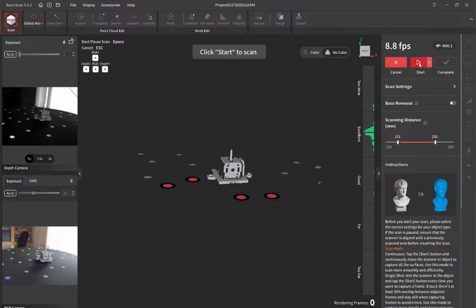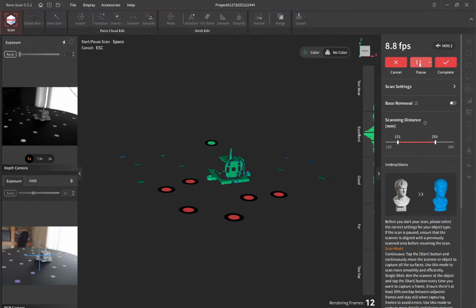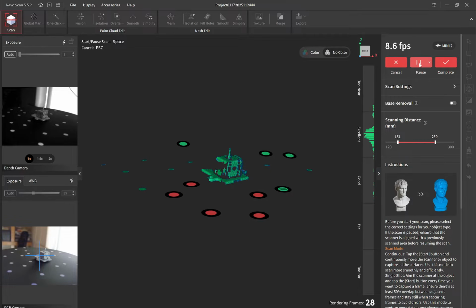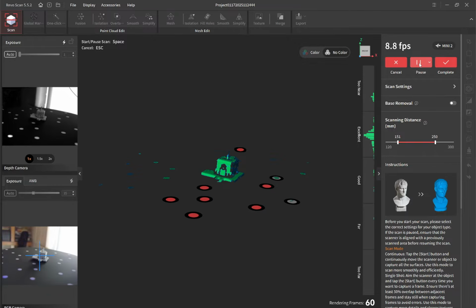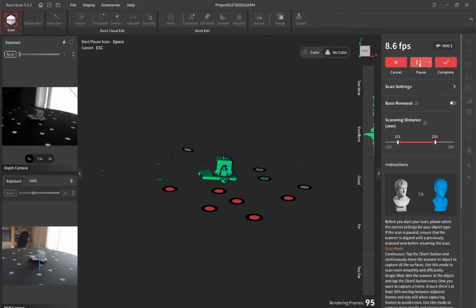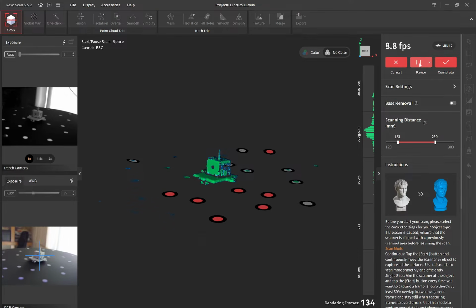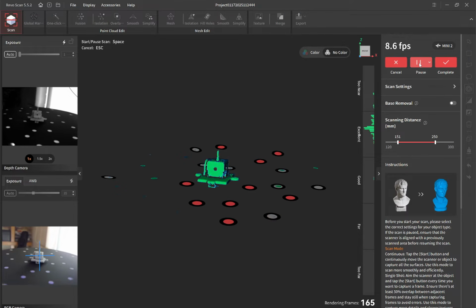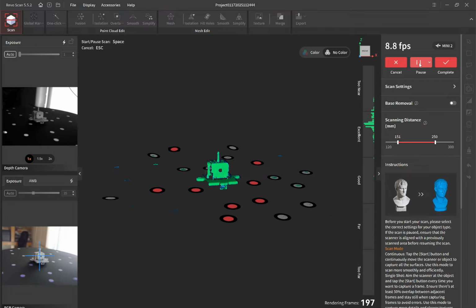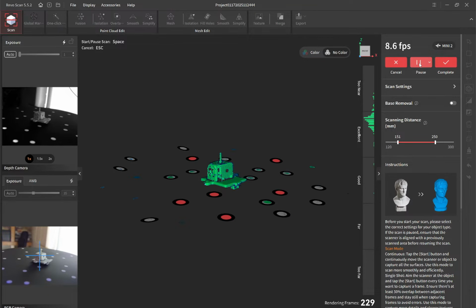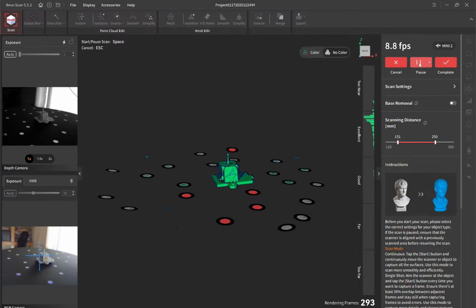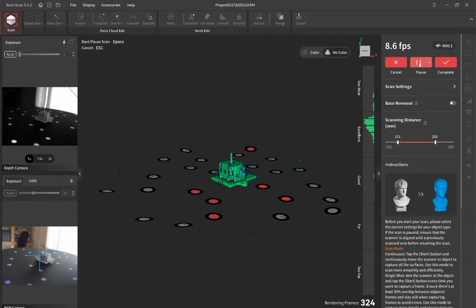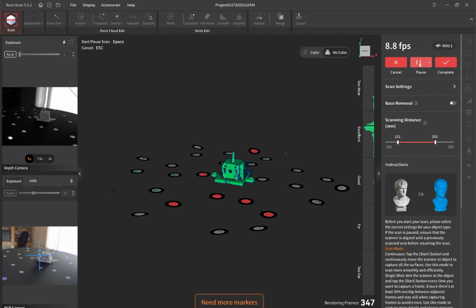The update specifically focused on auto exposure. What's happening now is that the scanner is doing a 360-degree rotation. I'll capture about 450 to 500 frames, which I believe is sufficient for this object, and will allow it to appear fully, at least the visible faces. There are moments when it seems to lose alignment with the object, but it quickly regains it. The reason is simple. I'm scanning at a very low angle, almost parallel to the plane of the table. For this reason, this happens.